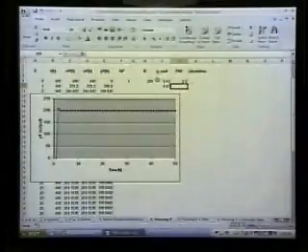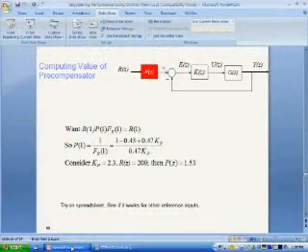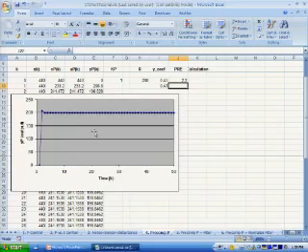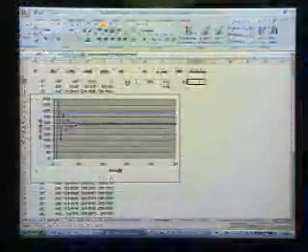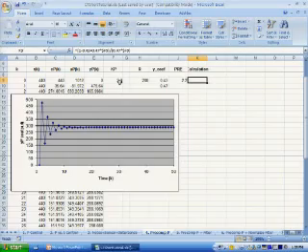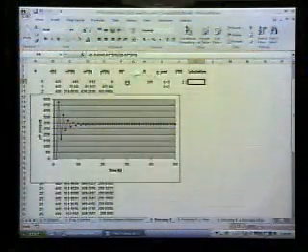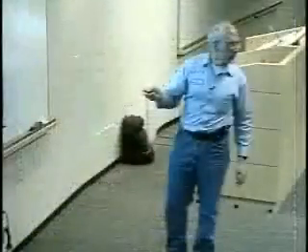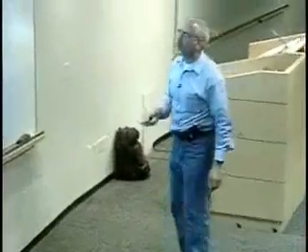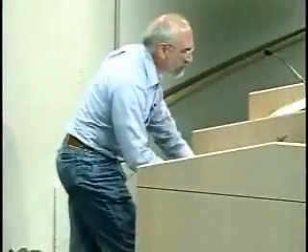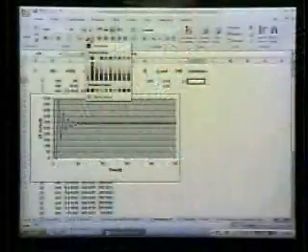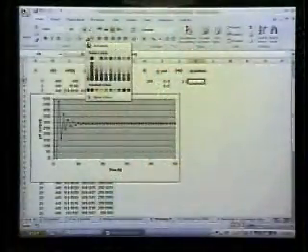I have to remember what I said, 2.3 for KP, right? So if KP is 2.3, then what I want to do here is I want this calculation up there that's on the line right here, because this is 1 over the transfer function, evaluated at 1. That's what I want. And that ends up being, if I reveal the secret here by changing this from a white font to a black font, 1.52.